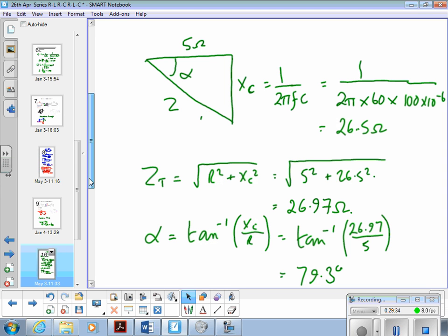Increase. So the point I'm making is these two components, inductor and capacitor, work opposite to each other. So if you've got both in a circuit, which we're coming up to in a minute, one will cancel some of the other to give an overall result. So a circuit that's got both components in can be overall capacitive or overall inductive, dependent on which reactance is bigger, as you're going to see in a minute.